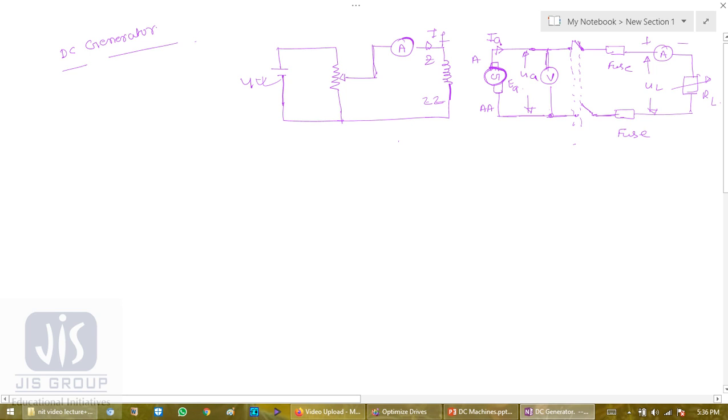So IF is not dependent on IA and the armature voltage, which implies that any change in armature current or armature voltage does not change the main field flux phi m set up by the field current. So this IF is responsible for setting up the field flux. Okay, so if there is any change in this current IA, it has no effect on this IF, or rather main field phi m. Okay, so what should be the equation?